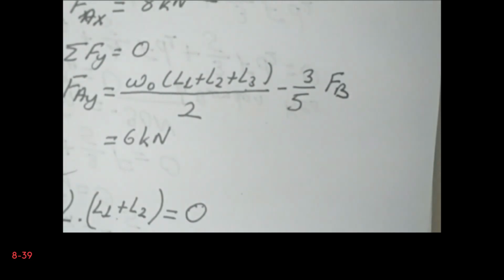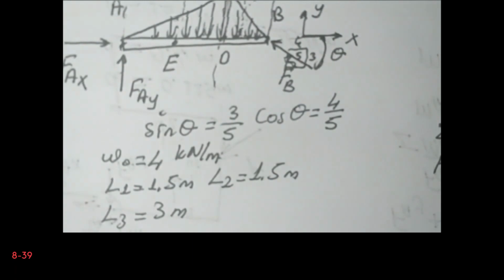Okay, now we have found the support reactions. Now, in fact, what we need to do is to determine the internal forces and moments which generate the stress. So what we are going to do is we will cut at an arbitrary location between A and B, and we will write the expressions for the shear force, bending moment, and normal force.